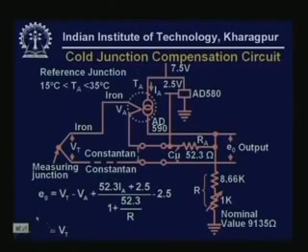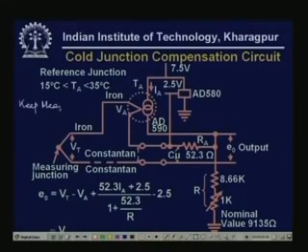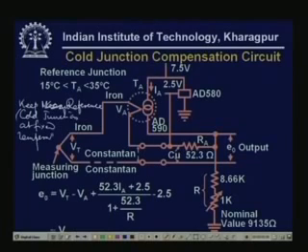That's why I'm wondering. So anyway, you see there are basically two strategies if you want to get the temperature of the measuring junction. One strategy is to keep the reference junction at a fixed temperature, such as 0 degrees. One of those junctions is called the reference, or sometimes the cold junction. That's one way, but that is cumbersome, because you need to maintain the temperature there. So you either have to put it in a small oven, or you have to create some ice bath in which you are going to dip it.